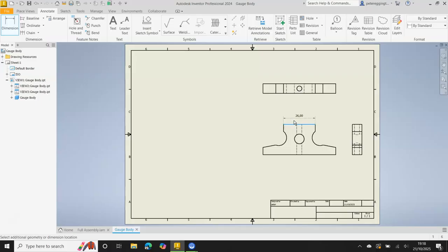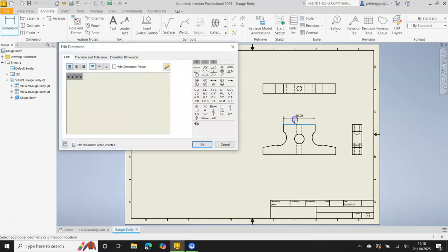When you put a dimension on, you'll notice that sometimes it jumps to a certain position. It'll go kind of like a dashed line rather than a solid. Sometimes that's very useful for spacing measurements out. In some cases you're trying to put so much information on there, you may just need to click where you want to put it instead.